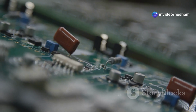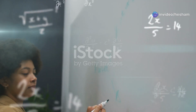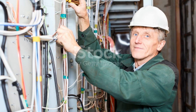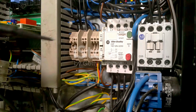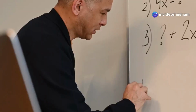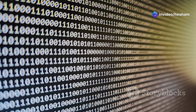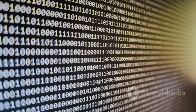Designing a combinational logic circuit is like solving a puzzle. First, you need to define the problem you want to solve. Let's say you're designing a circuit to control a sprinkler system. You'd need to decide what inputs the circuit should have, like a rain sensor and a timer. Next, you would create a truth table. This table lists all possible input combinations and the desired output for each combination.